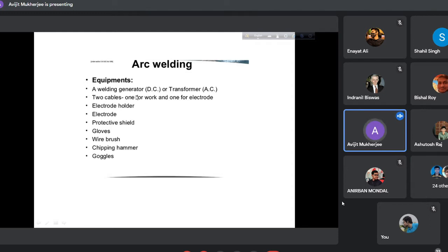Now, in arc welding, as we mentioned, heat is the basic minimum requirement in welding. So how is heat generated in arc welding? As the name suggests, it is an arc, obviously obtained from electrical sparks. Using electricity, we may also have electric resistance welding, where the concept is different and the heat is H equals I squared R T. But here, how heat is generated, we shall discuss.